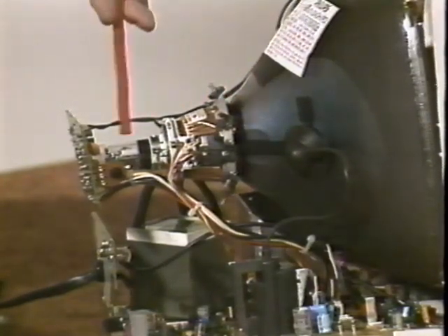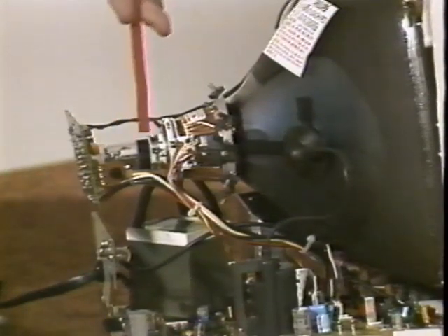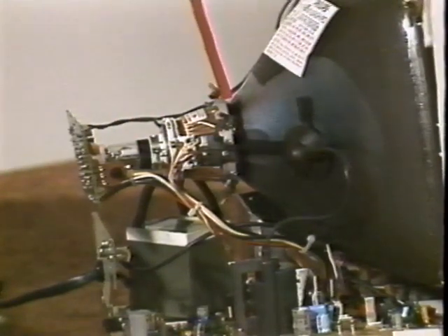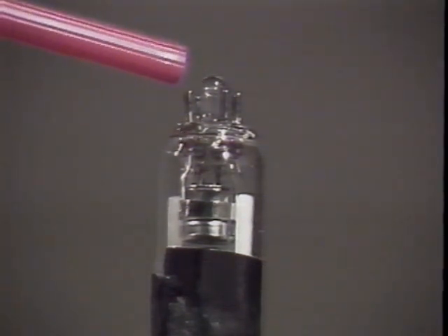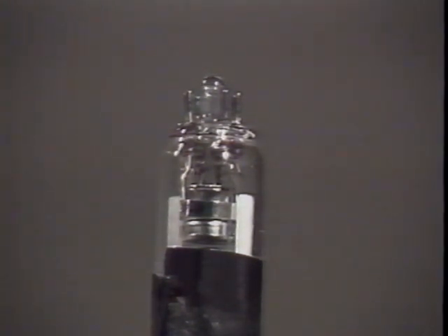The thin area towards the rear of the tube is called the neck. The electron gun is inside this area of the CRT. Although it looks like a convenient handle, never pick up a tube by the neck. This can breach the tube's sealed environment, resulting in an astonishing and dangerous implosion. The nipple is a small protrusion of glass at the rear of the tube, surrounded by the CRT's connecting pins. Cutting the nipple off of a tube disarms it by letting air trickle in.